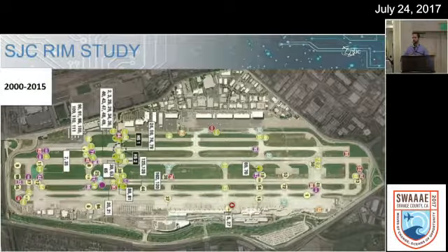So, we already have a modification to standard for when we were operating that former 11/29. So when we're taking a look at the potential alternatives we can do on the west side, there's a lot that we could reconfigure, and whether that's reopening the runway and eliminating a taxiway, or closing the runway for good for safety reasons and bumping out the FBOs, I think regardless there's a good chance that we will mitigate those taxiway connectors and the issues we've been having with that, especially through putting islands out there and getting those 90-degree turns and that type of stuff.